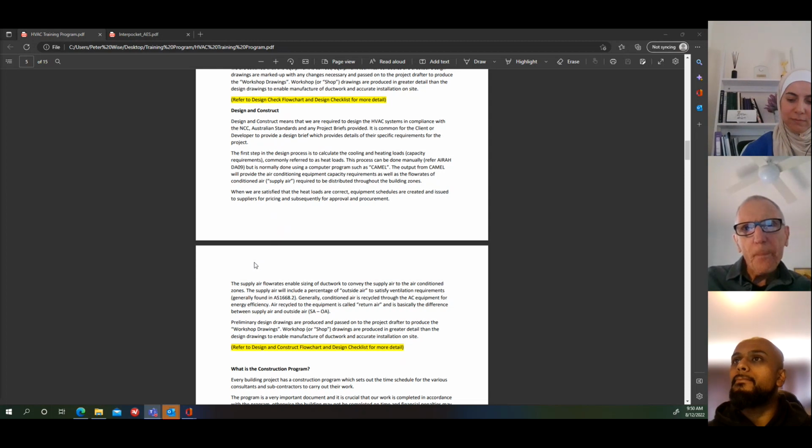So for instance, a restaurant might be 300 watts a square metre because you've got cooking, you've got a lot of people in there and so on. A laboratory could be quite low because really there's not much heat load in there. So on and so on, like a computer room, data center or a comms room might be 500 watts a square metre because there's a lot of equipment generating heat in a small space. So it just gives you an idea of what the answer should be.